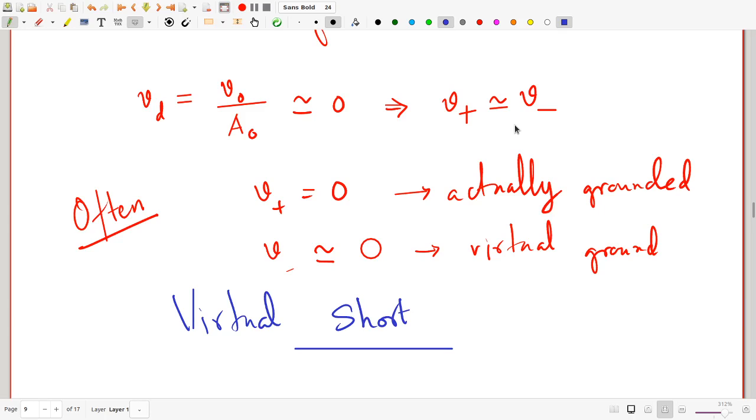The one problem with that nomenclature, of course, is that if you say that 2 points are shorted, it would tend to imply that any amount of current can flow through that and you will still get a 0 voltage difference. However, op-amps have huge differential input impedances, which means that no current or almost no current flows in between the two inputs. Now that would be sort of contrary to the terminology short.